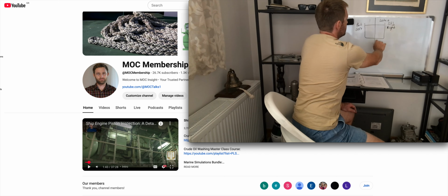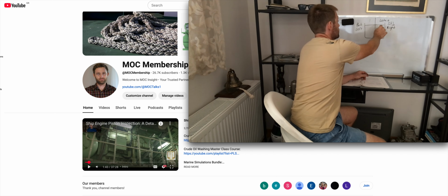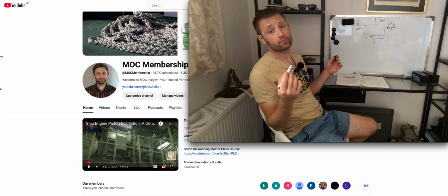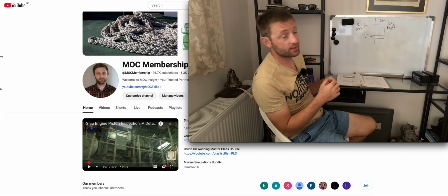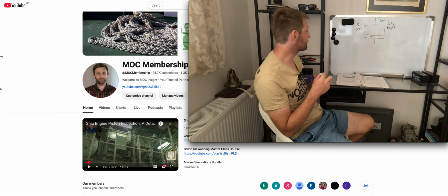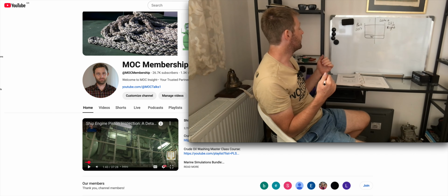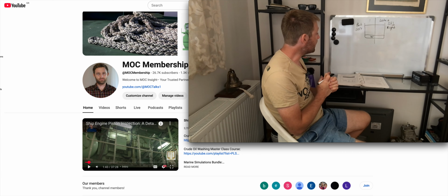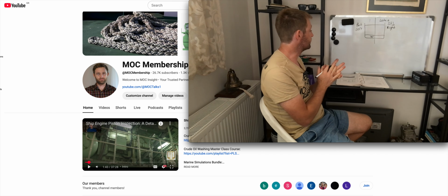So when we have list 0, that means we do not have any inclination to the left or to the right, port or starboard. And at the bottom here we have the water, which can be free water, which can also be traces, which can be emulsion. We don't know when the vessel arrives, but we are able to know what that is. If we take some samples and make some measurements, then we are able to estimate what kind of water that is.